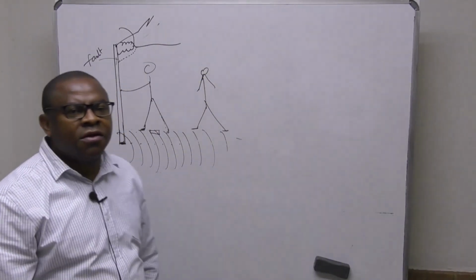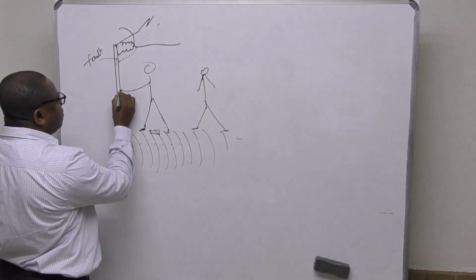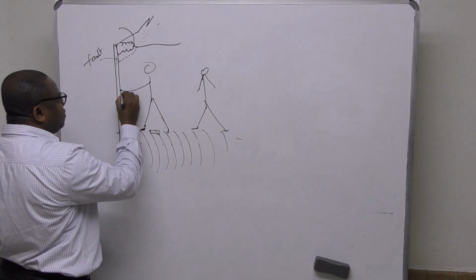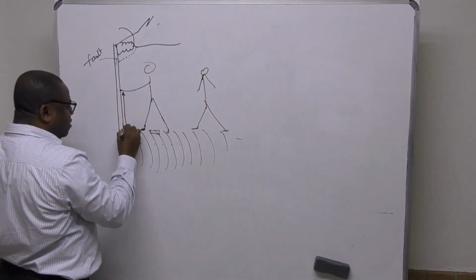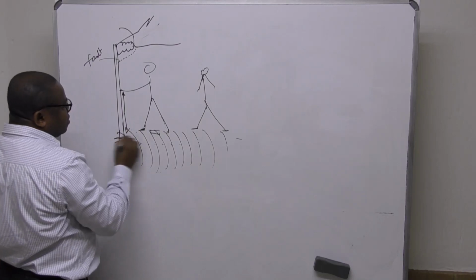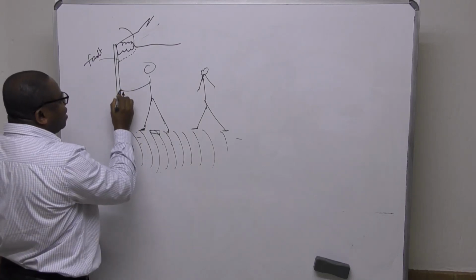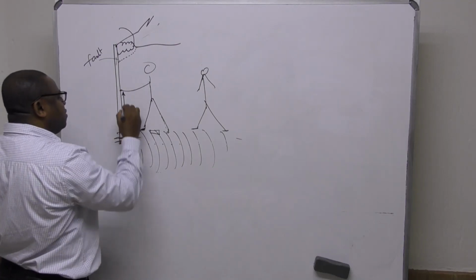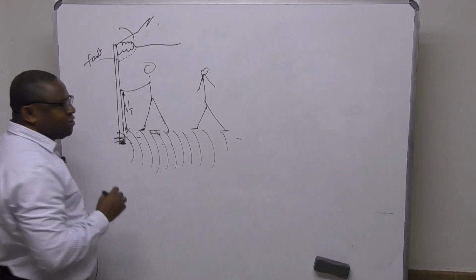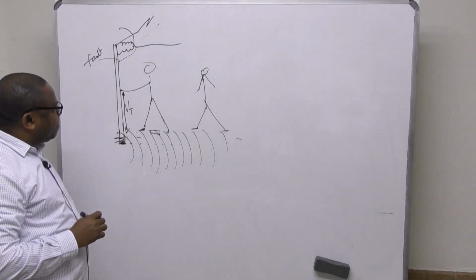definition, a touch voltage. As this guy is touching this, there's a voltage difference between the point he's touching and the earth, because this is earth. All right? So now the current coming down here will decide, can I continue like this or can I go this way? This voltage difference is what we call V touch. All right?